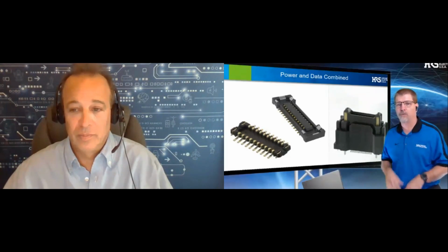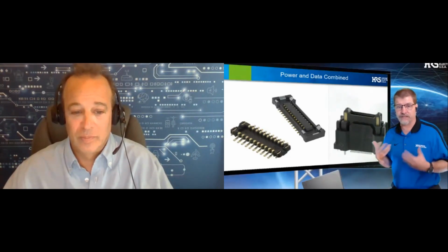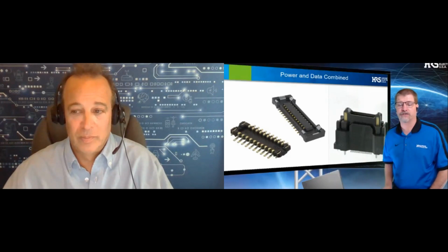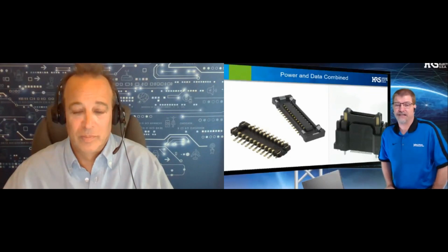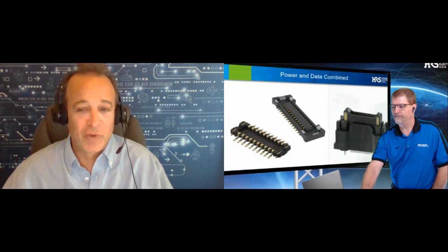This is super important if you're putting more than one connector on a board. And specific to power connectors, you'll note on the end here, there's a power contact. There are actually 4 power contacts on this connector. The standard rating is 3 amps, but depending on what you're running through the center, we can design this for applications that go up to 5 amps per contact. So that's a pretty cool product. It is indeed. Any other questions, folks?